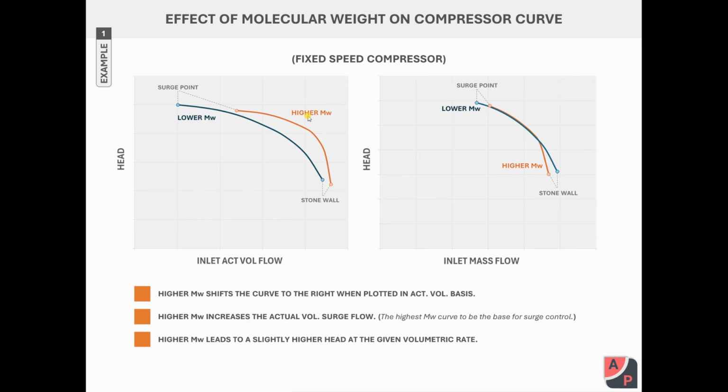Based on these non-dimensional numbers, you can scale the curves when the inlet condition is changing. I may have a session introducing the Buckingham Pi theory for compressors and pumps and maybe other equipment.